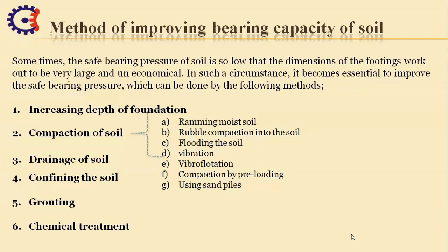Next is the compaction of the soil. If we compact soil using an appropriate method, then there will be an increase in density and shear strength. As a result, the bearing capacity of the soil also increases. There are many methods of compacting soil, like spreading broken stone, gravel and sand, thereafter ramming well in the bed of the trench, then using appropriate rollers as per the soil type to move at a specified speed, then by driving concrete piles or wood piles and withdrawing the piles.